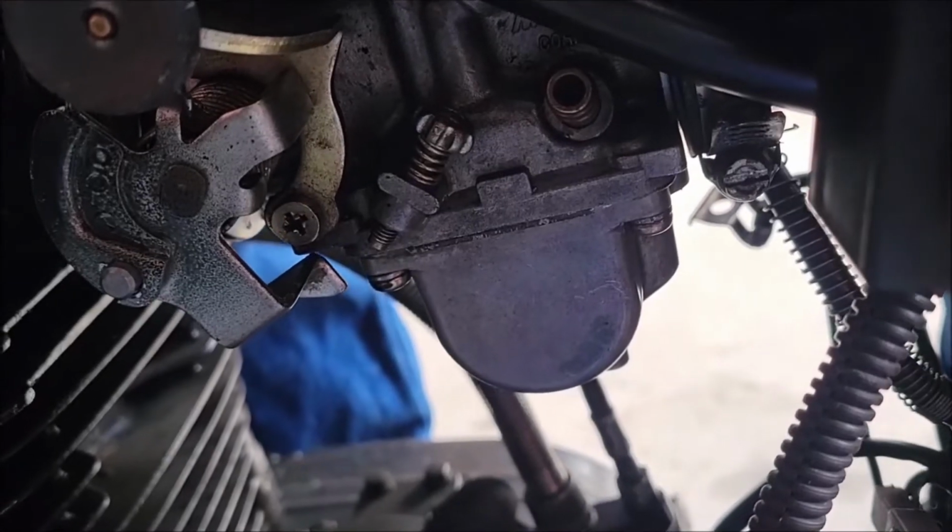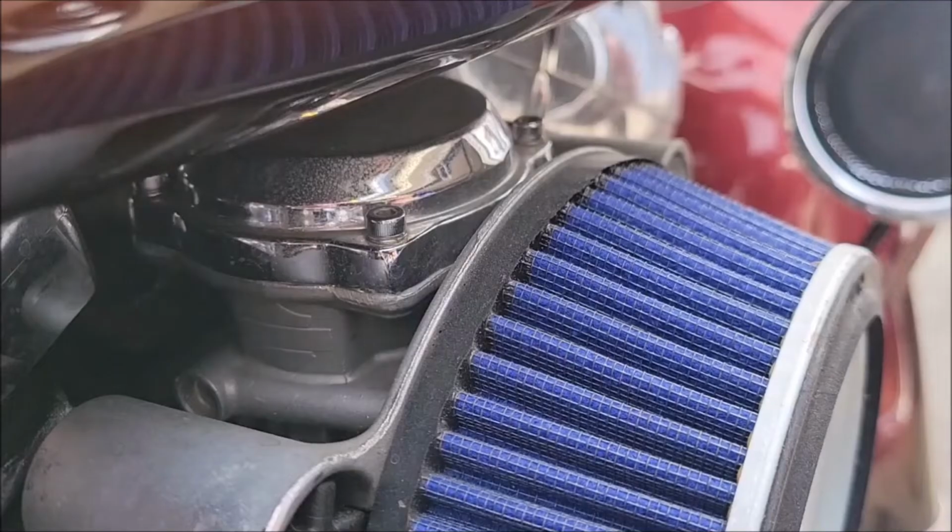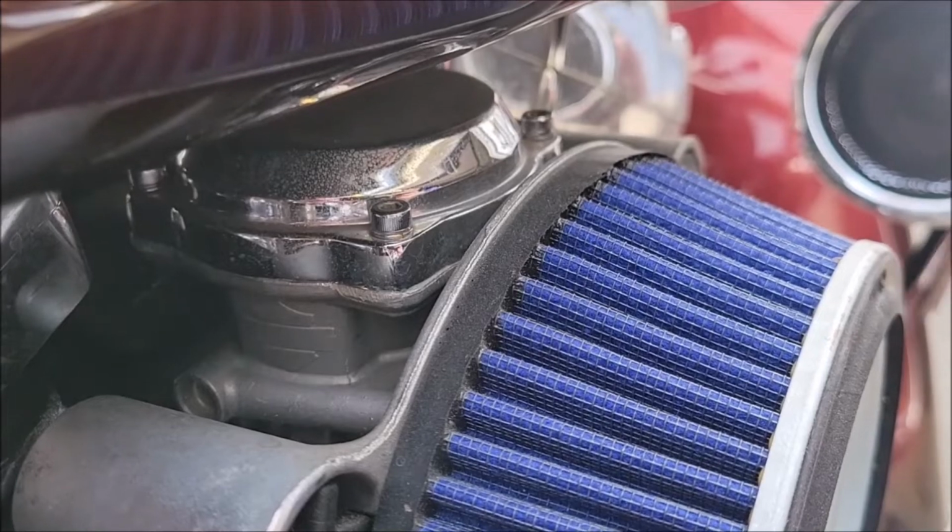To sum up your carburetor in a single sentence, the carburetor simply mixes fuel with air to operate your engine. This is because your engine doesn't just run on pure fuel. It actually needs fuel and air. Put together, this is an air-fuel mixture. There's an actual ratio at which your engine will run best. This is called, and the pronunciation on this is really hard, the stoichiometric ratio. This ratio is 14.7 parts of air for every part of fuel.